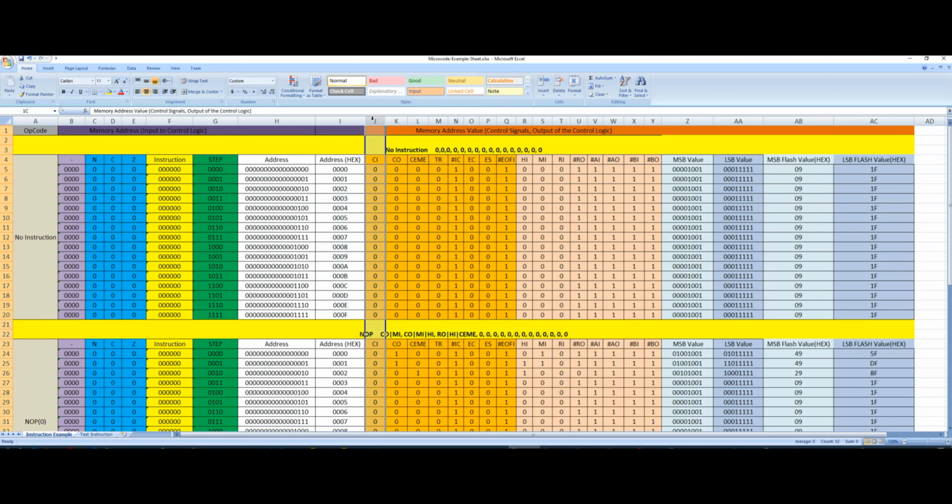And the next section is actually the data that needs to be written into those flash memories. Now, if you look at the data side, I actually listed all the available control signals. So the first set is related to the most significant chip, and the following, the pink area, is related to the least significant chip.